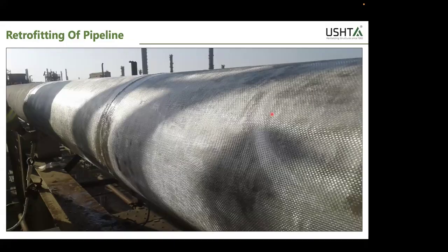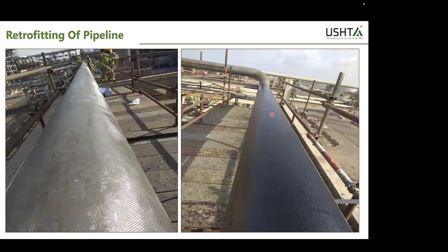Otherwise, what will happen is the carbon will conduct and be in contact with steel, and there may be a chance of fire, or carbon can get damaged also. So this is the installation we did. And then later on, we applied multiple layers of carbon.